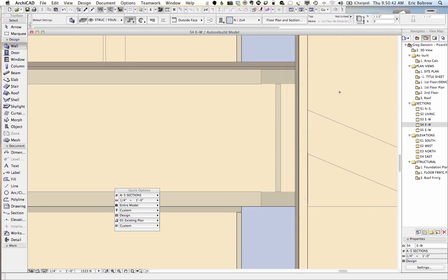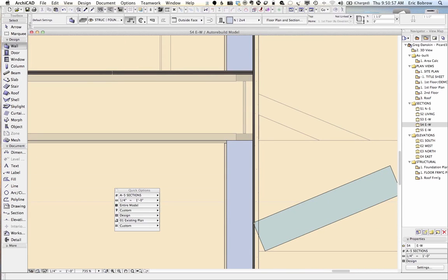Okay, so the lesson here, and we've taken a good chunk of the coaching call on it, is that it is so critical to understand how these building materials, when they're used properly, can essentially help you to get sections to look correct. You need to draw with a composite, so that's why I said we're creating this entire floor assembly as a composite, because then the walls can interact with it properly.